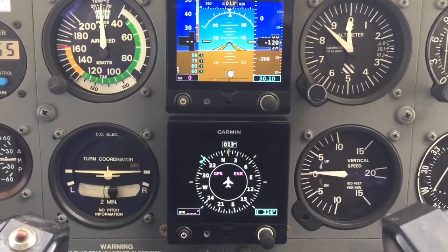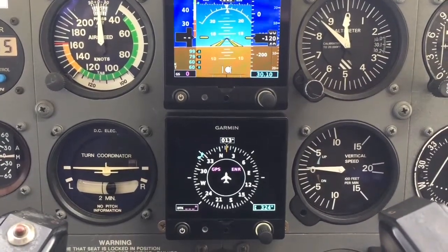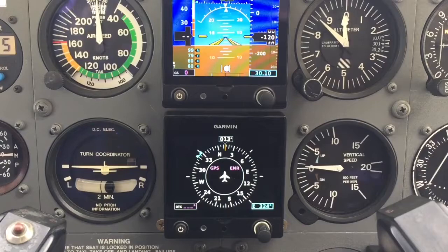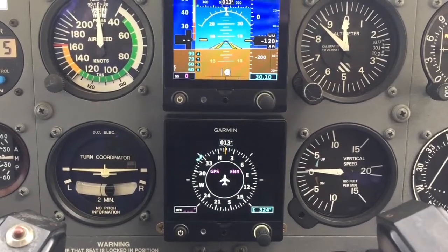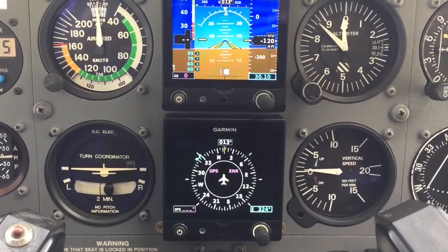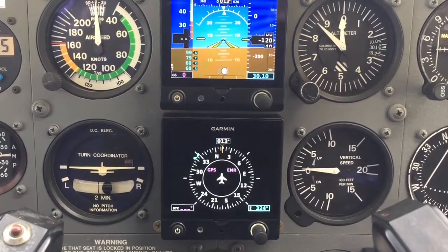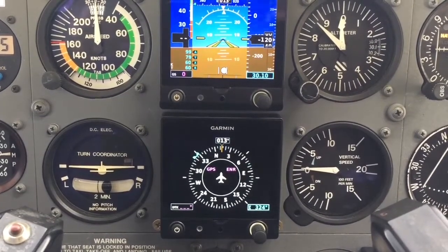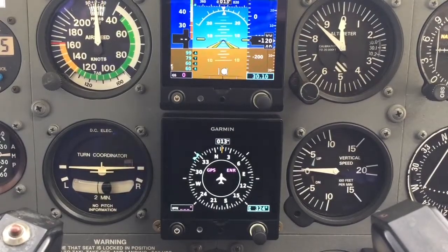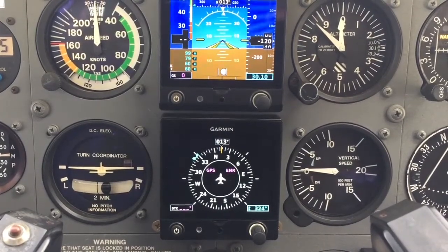The G5 HSI is directly connected to the avionics power bus and will automatically power up and down with the avionics master switch. See Figure 4.0 on the Hodge Flight Service website or in the aircraft binder for a complete system diagram.